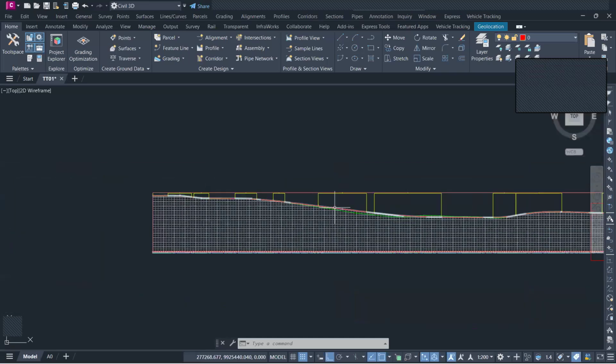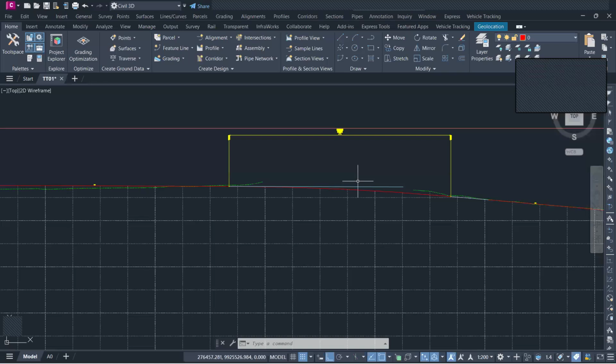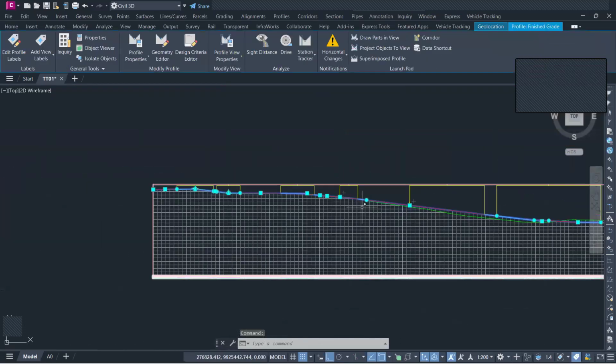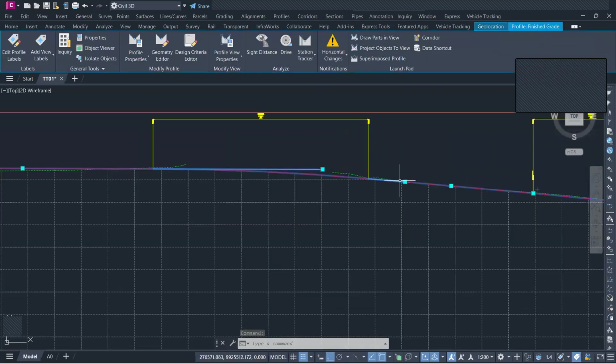So the geotechnical report isolates sections that have good material that can be reused in other sections and isolates sections that have poor material. So as you're designing, that is where you will now come and say, for example, this section has a very good material and therefore I want to reuse it. Therefore, what can I do?